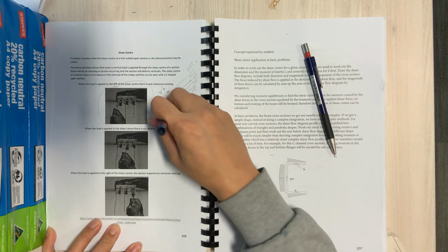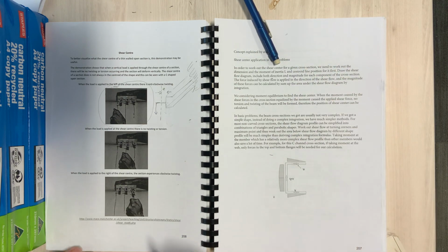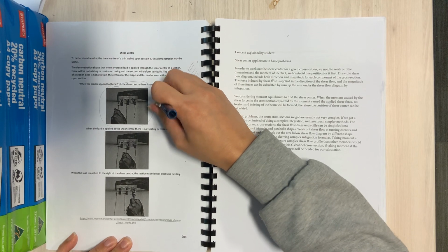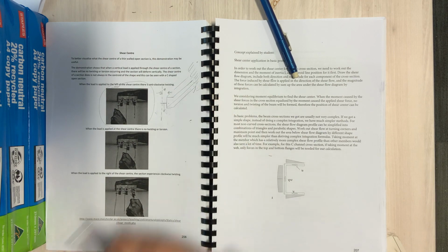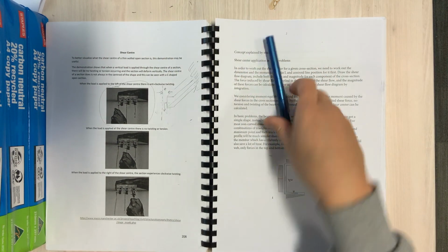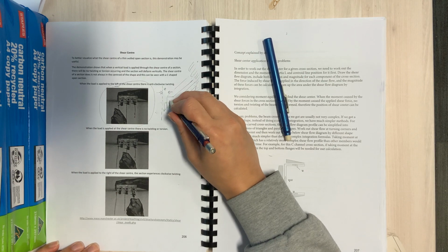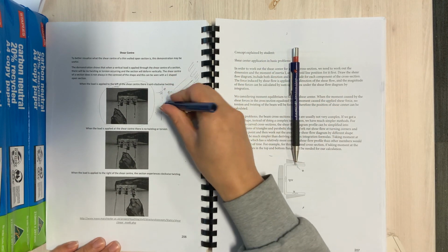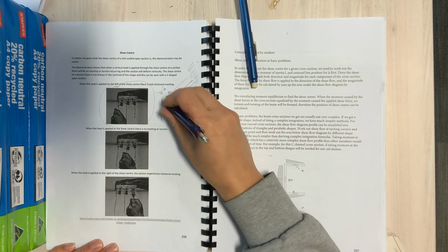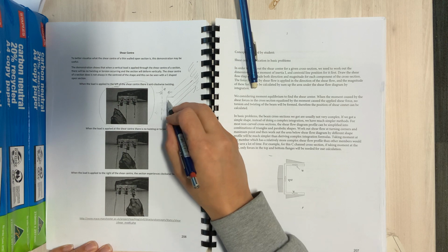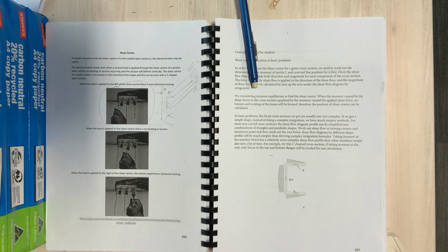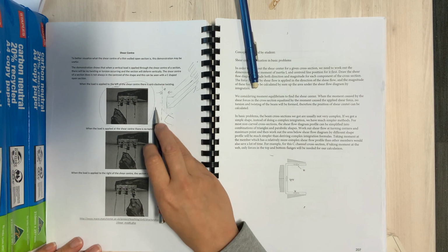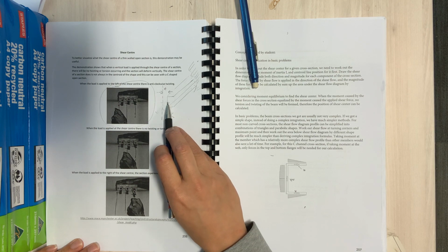Okay. And then the final example is if the load is applied to the right of the shear center. So if the bracket now is a bit different and the load is applied to the right of the shear center, maybe through that point there, or in real life the load might actually be applied through the web, since that's where you're putting your screws in, but anywhere to the right of the shear center, and again you pull it downwards with a string. This time the section would rotate in that direction. Okay, so there is this point which is the shear center, and it's not the centroid. The centroid is there.